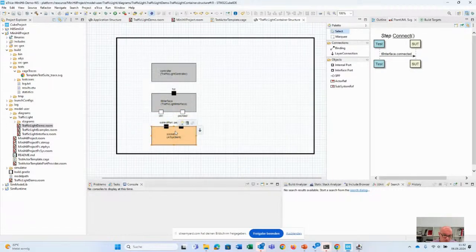So now, separation of concerns. I separated the control for the TCP/IP socket, to configure the socket, the IP address, the port, and so on, from the payload. Why is that? Separation of concerns. I might be forced to use another protocol in the future, and I can reuse the payload protocol, not the configuration, because UART, for example, is configured differently than a TCP/IP socket. I can use the same payload. So separation of concerns for reusability.